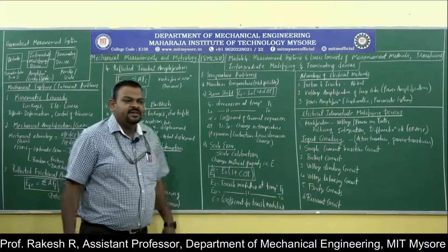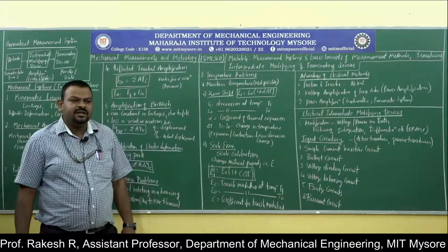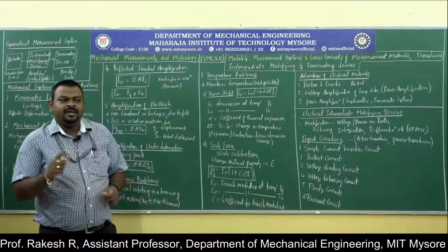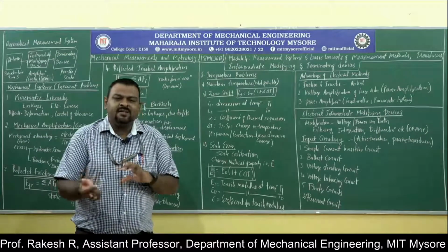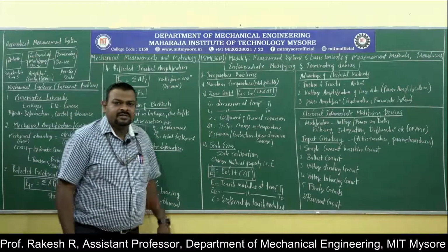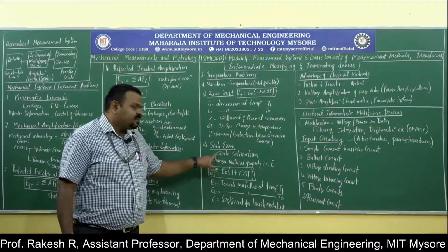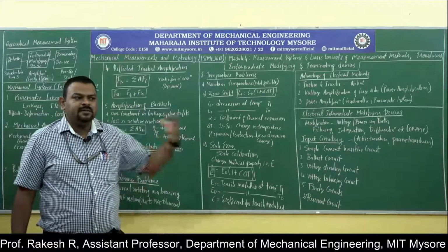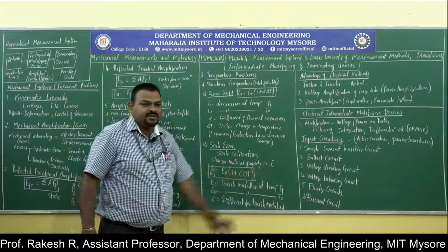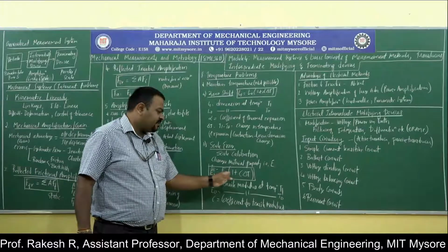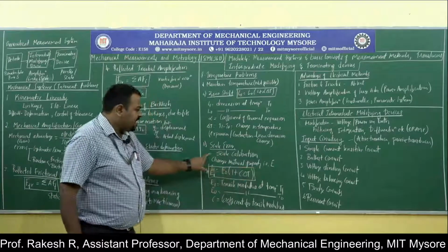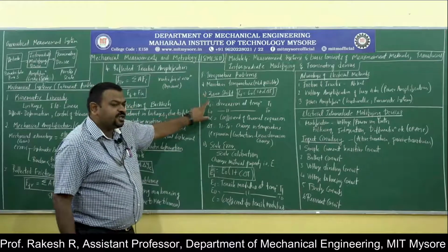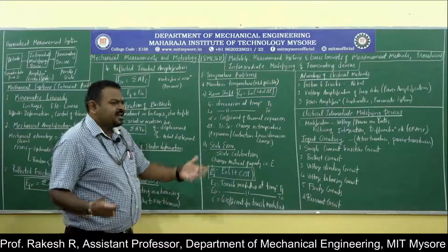Then next is scale error. Scale calibration is very important in almost all cases. Because of this, with scale error, the pointer may not move, or the temperature scale may get affected. Like this, there are several things, and scale calibration must be done frequently. Scale error depends upon the material's elastic properties like Young's modulus, and the equation is E1 = E0(1 + C ΔT). Scale error is measured in terms of modulus of elasticity, and zero shift is measured in terms of linear dimension or any dimension.